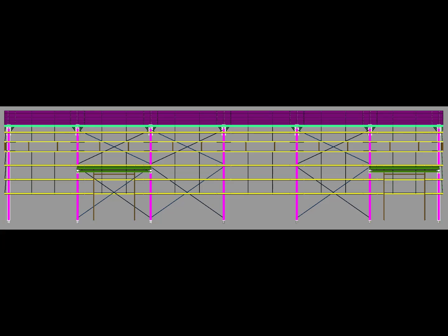So, let's summarize what we learned from this slide. First, we are now looking at the side wall framing of the real PEB model. Second, the vertical members form the main steel column system. Third, the horizontal members form the secondary side wall framing. Fourth, the sag rod is a secondary member associated with this framing system. Fifth, the X-shaped diagonal members should be distinguished from the sag rod because they represent the rod bracing arrangement.